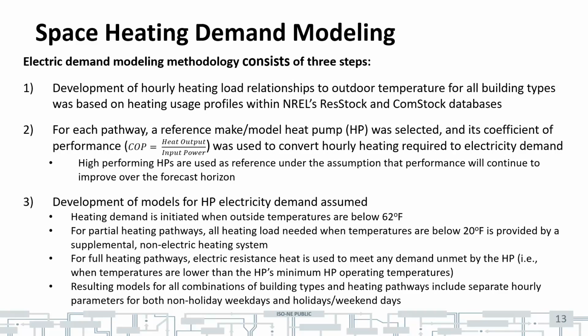And then some details for full heating. There's electric resistance backup that's used to meet any of the demand that's not met by the heat pump, basically when temperatures are below the minimum operating temperature of the heat pump. And basically we ended up with these hourly models for all combinations of building types and heating pathways.